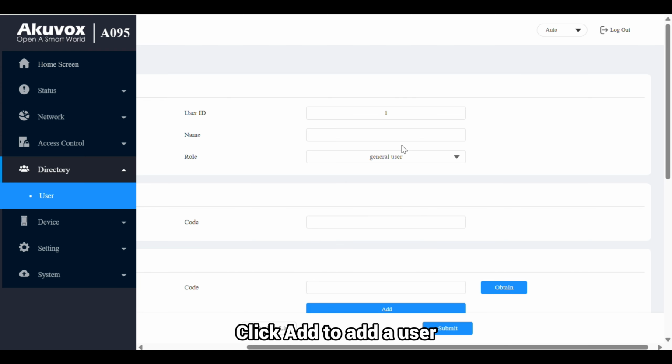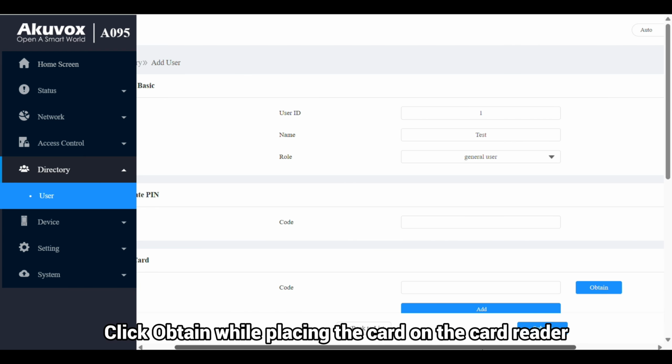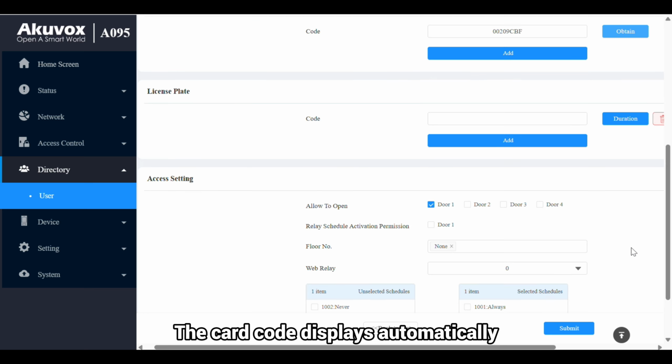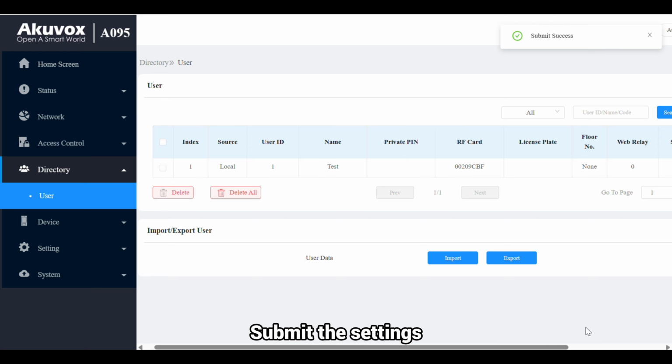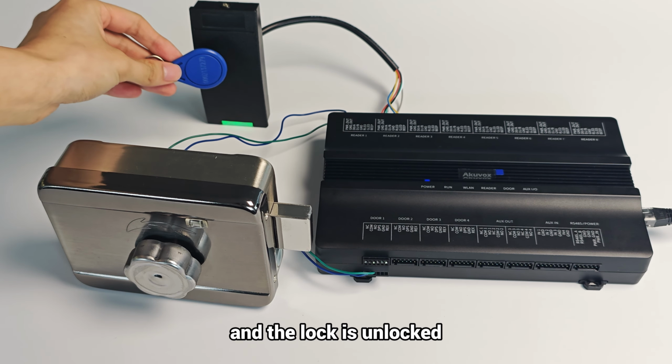Click Add to add a user. Enter the username. Here we assign a card to the user. Click Obtain while placing the card on the card reader. The card code displays automatically. Scroll down to the access setting part and check the door to be opened by the user. Submit the settings. Now, let's unlock the lock. Swipe the card, and the lock is unlocked.